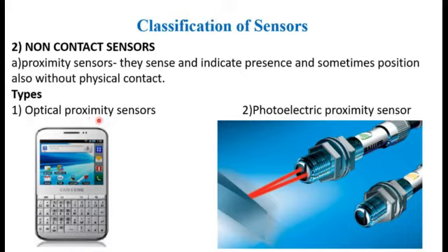These sensors detect objects directly in front of them by detecting the sensor's own transmitted light reflected back from the object surface. Here we can see the sensor transmits some light and detects the back reflection of this light. Whenever there is an object in front of the sensor, it reflects the light from that object, and the sensor detects the physical presence of the component.